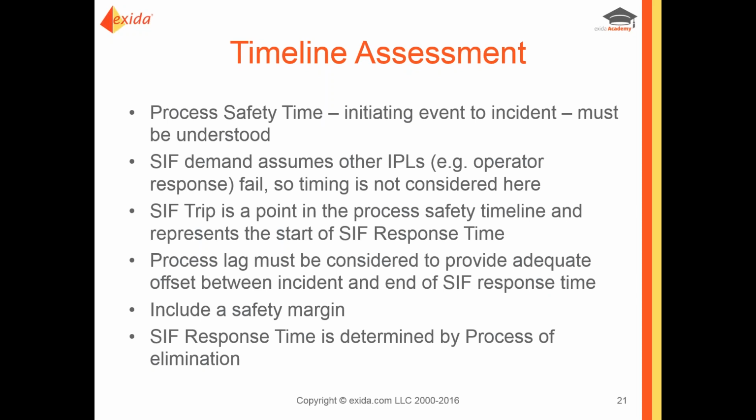It may take some sophisticated modeling tools such as Aspen in order to calculate the process safety time. In the case of runaway reactions, it may be necessary to do calorimeter modeling in VSP or RSST or ARC type testing, or to do blast calculation modeling if it's something like a combustible dust that we're concerned about. So quite a bit needs to go into determining this process safety time and looking at the rate of propagation of the incident.